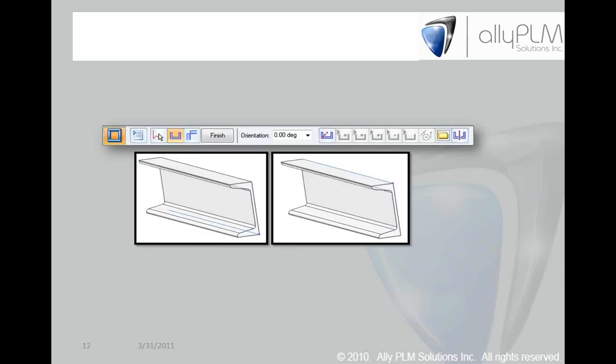And we did cover this one. It was the flip option. Now in this case, you'll see on the left screenshot, this cross section is attached at the bottom right corner. Now if you don't want it, you can flip this over, and it just creates a mirror image of that cross section. So that's another way you can manipulate the way cross sections are attached to your sketch.